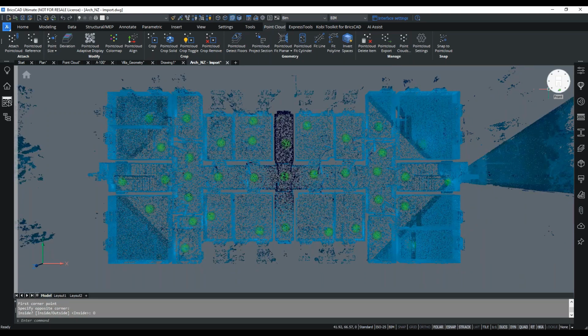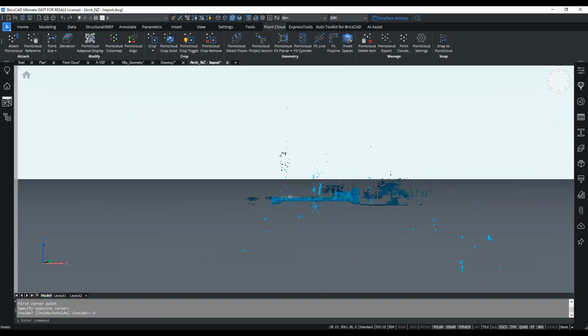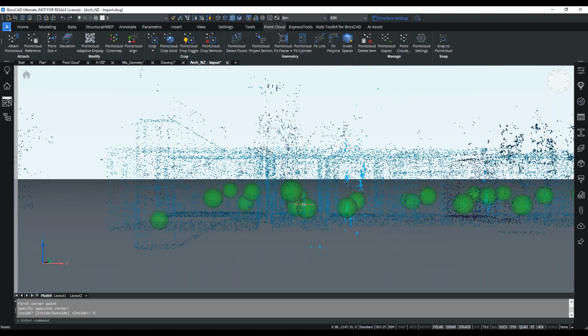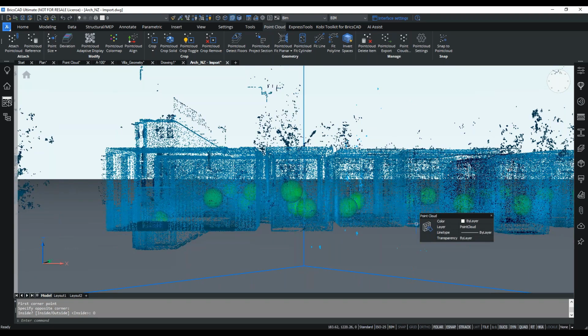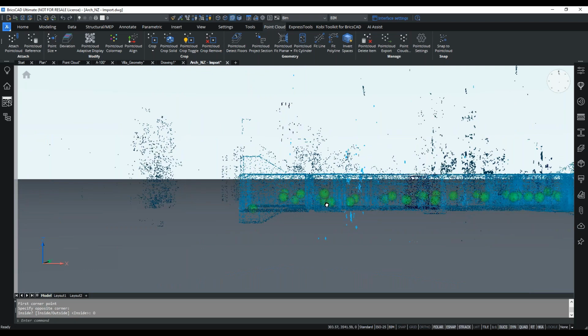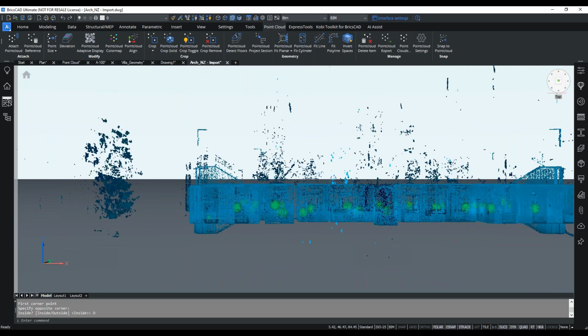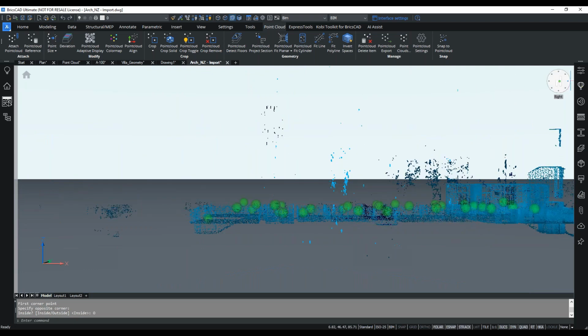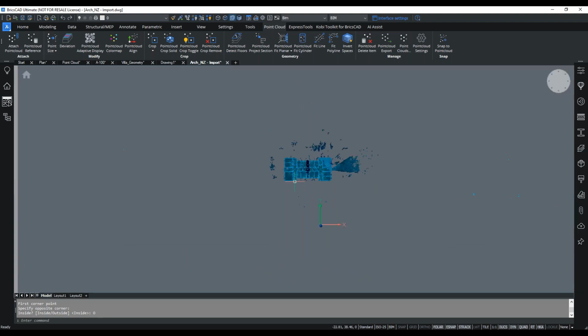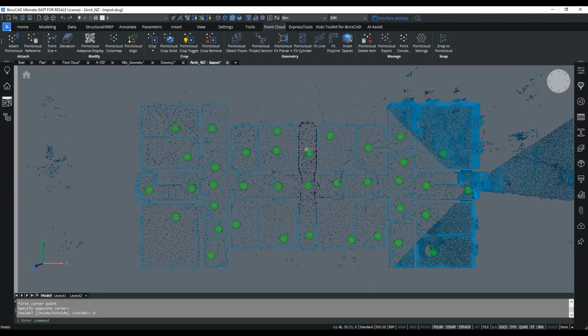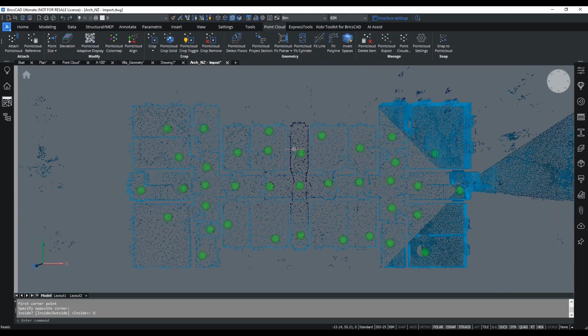Okay, what we then do is go to the front view, and in here you can accurately identify the elevations of the floor, of the roof, and of the windowsill levels, etc. Now in my case, this isn't a production job, so I'm not too concerned about getting it accurate, but I'll accept the defaults that the software suggests. But if you were doing it more seriously, you would go and check those before you start doing the work.